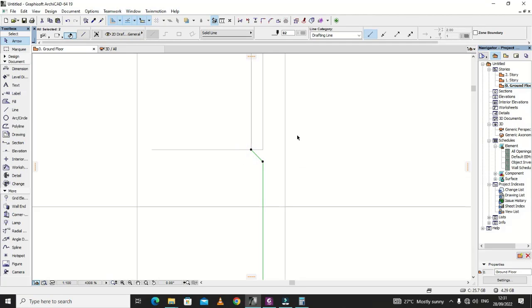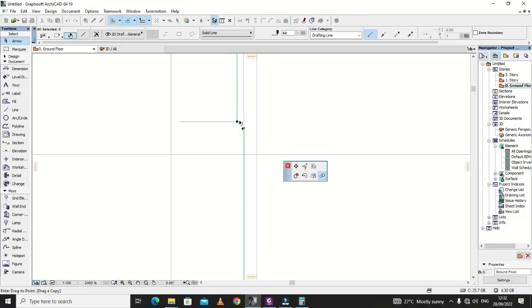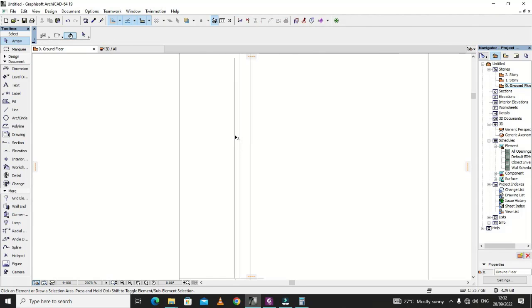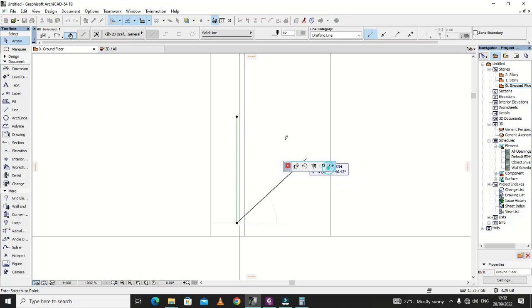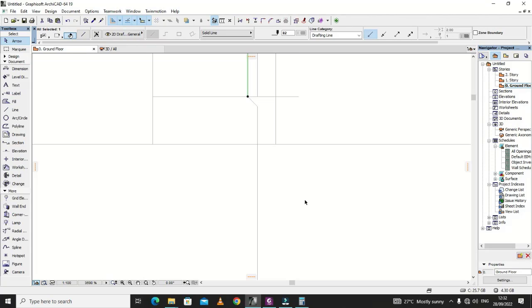I'm not going to draw this again. So I'm just going to copy this, and maybe let's make this a little bit short, and this one a little bit longer, or let's just maintain it the way it was. So we shall carry this and multiply it, and bring it here like that. So for this distance of this bar, we are going to increase it from 600 to 800. Why? Because this is a D16 bar lapping with a D16 bar. So the smallest bar diameter times 50 is going to be 800. So yeah, like that.